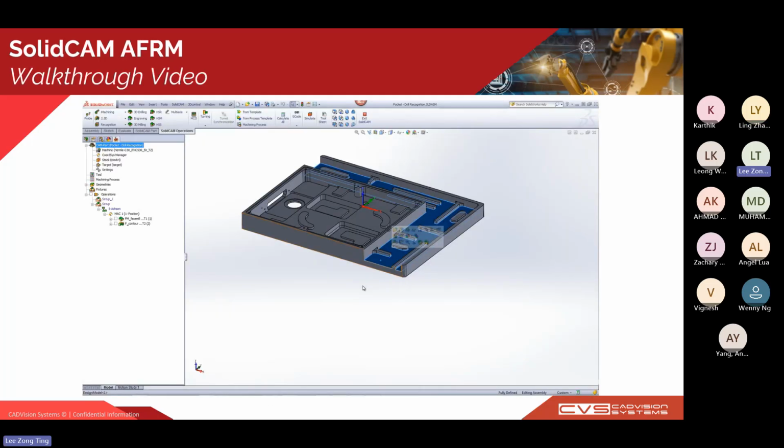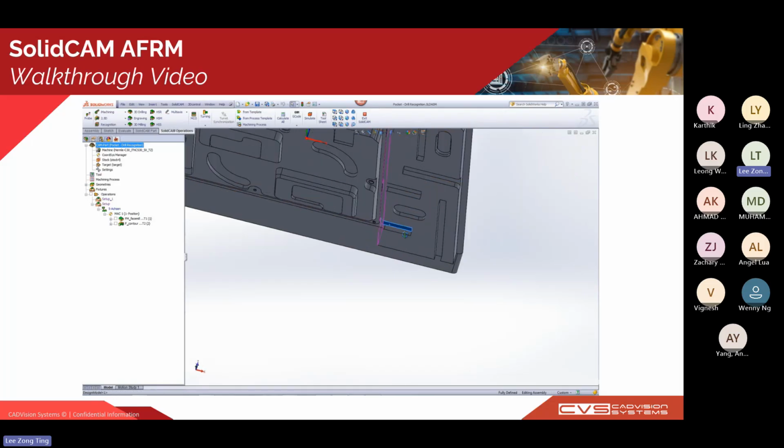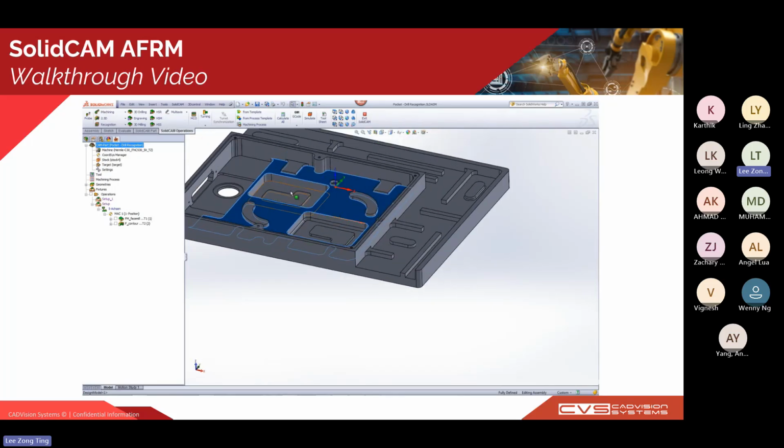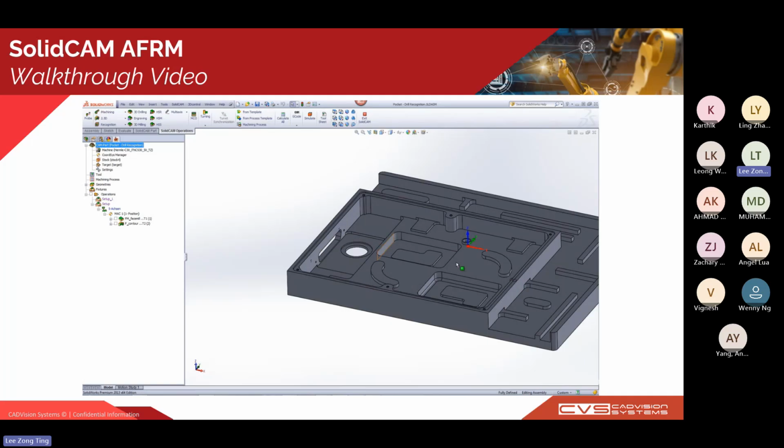Okay. So let's have a look at the live actions of SolidCAM AFRM, Automatic Feature Recognition Module. Let's start. You can see on this CAD model we want to machine, there are different types of pockets. We have an open pocket, and also pockets of different depths from the top until this island right here. Inside the part itself, we have another pocket, and inside that pocket, we have different pockets also. From the top, there is also a small step right there, which is also considered a pocket.